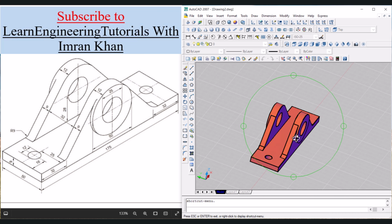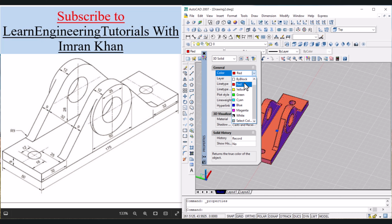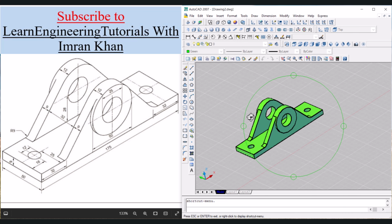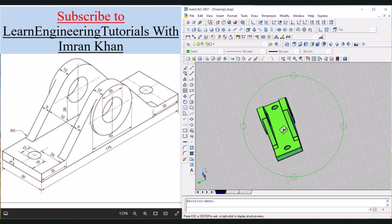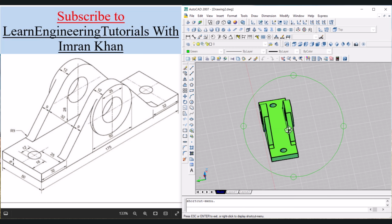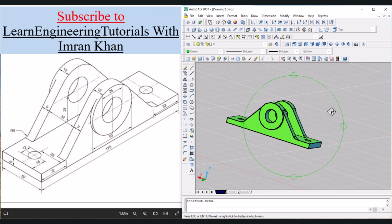You can just double click and change the color from this property menu as well. So click on green, and the object will be colored accordingly. Now click on this close option, click on orbit, visualize the object. If it looks okay, then we can end this lecture.